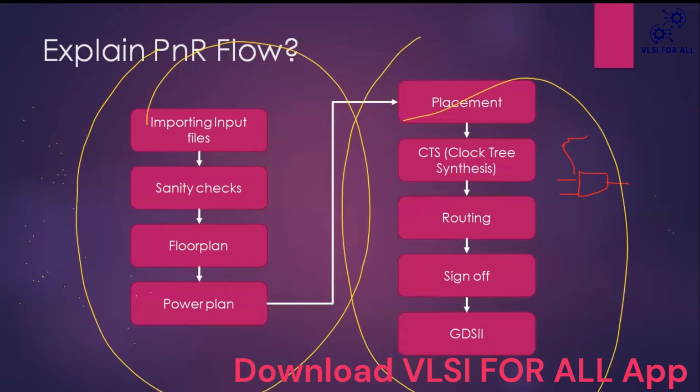Only if the design has multiple voltages do we need that UPF file. If the design has only 1 volt, or 1.2 volts, or 1.8 volts, then we don't need UPF. But if the design has multiple voltages, like 0.8 volt plus 1 volt, or 1.2 volts, then we need a UPF file, and we have to create some domains for those voltages.